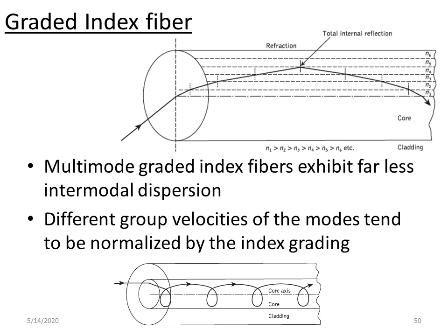But in the multi-mode, because of the different modes, there are different group velocities. Whichever ray passes through the center of the optical fiber has a very small length, but because of the high refractive index at the center in the graded index fiber, the velocity is less. If you go towards the cladding, the refractive index is lower, so the speed increases, but the length also increases. So speed and length compensate in the graded index fiber, so that all the modes reach the receiver end at the same time.